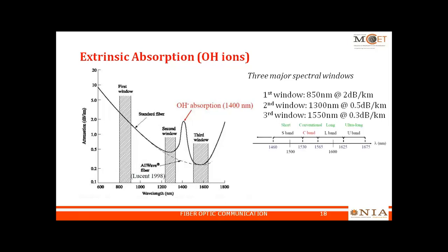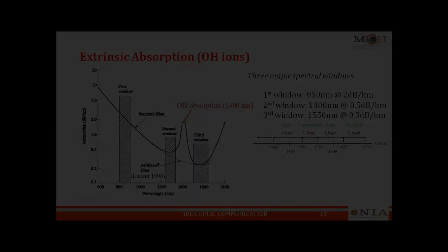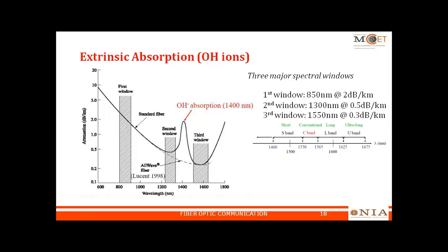Now signal dispersion. In conclusion, we can say that absorption causes attenuation, and dispersion causes error. Attenuation means there is a signal loss. Distortion means there is pulse overlapping, and because of that, error will be produced in the receiver. Attenuation or fiber loss we can eliminate by using repeaters as well as optical amplifiers.